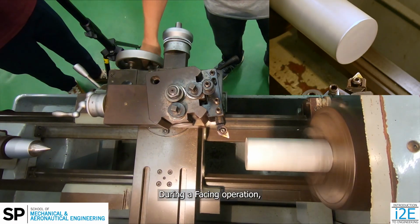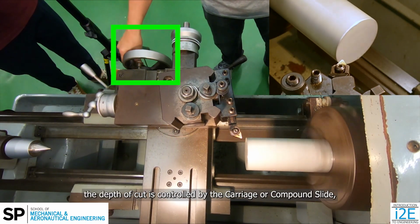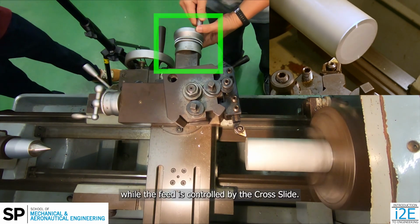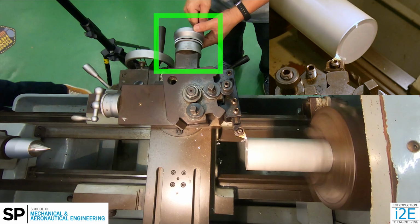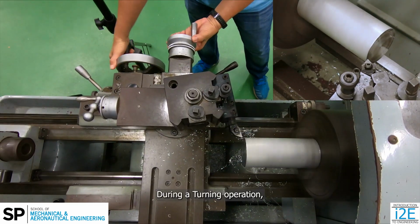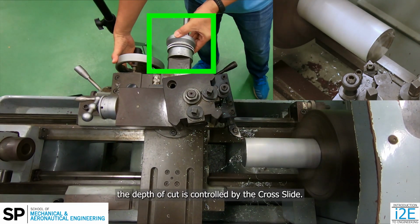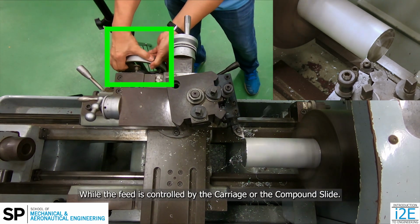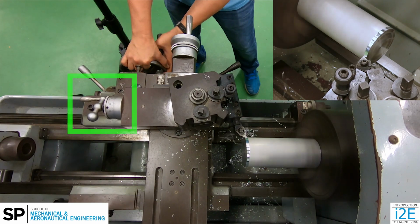During a facing operation, the depth of cut is controlled by the carriage or compound slide, while the feed is controlled by the cross slide. During a turning operation, the depth of cut is controlled by the cross slide, while the feed is controlled by the carriage or the compound slide.